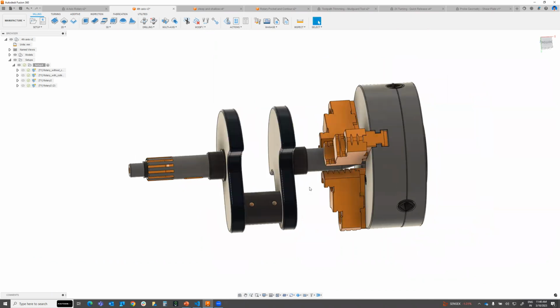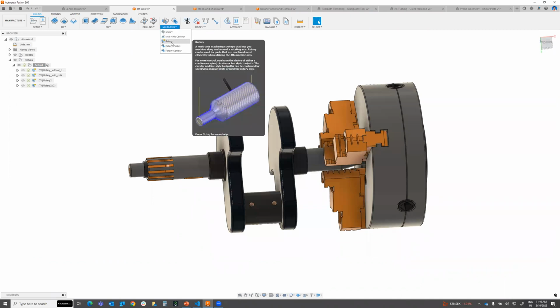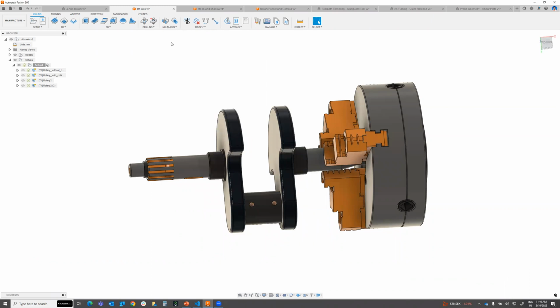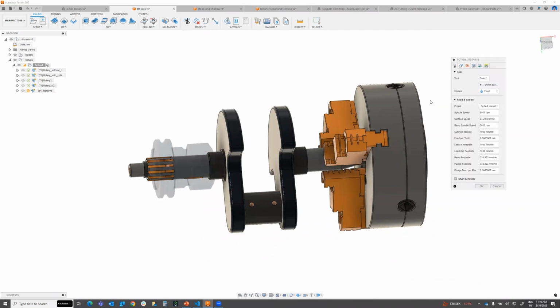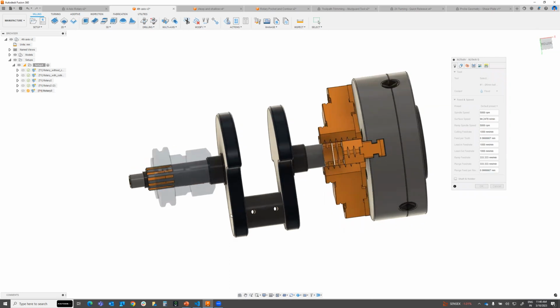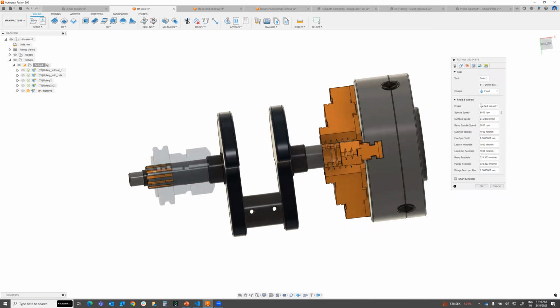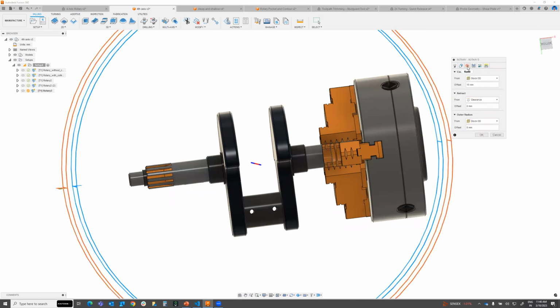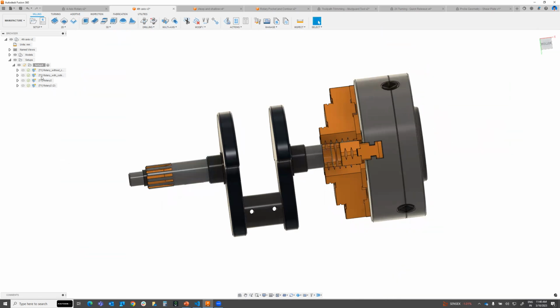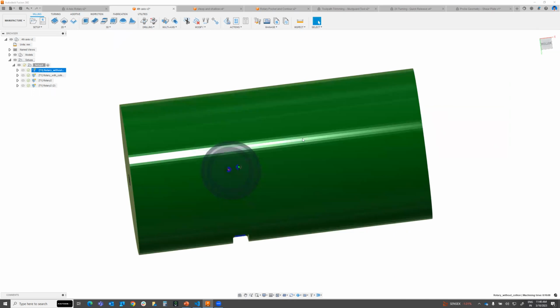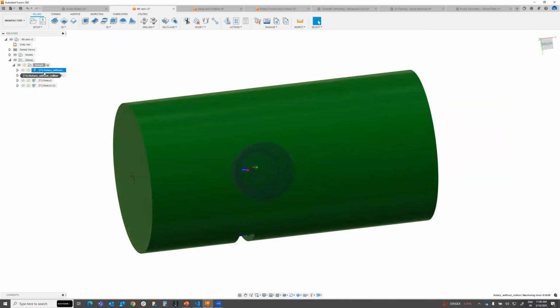First, I want to use the strategy for multi-axis, which we call the rotary. Okay, I just select the rotary toolpath. After that, we need to set my axis plane here. According to my axis plane, once you set the axis plane and the geometry, you can go for the toolpath for roughing.